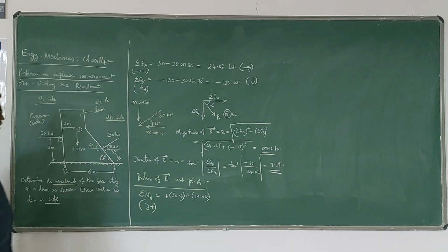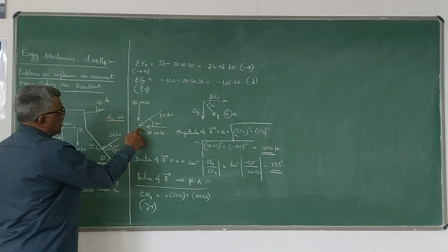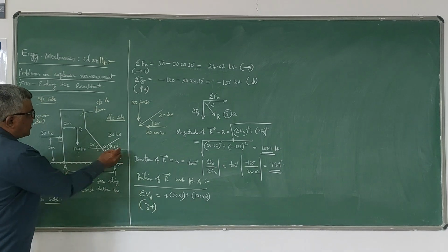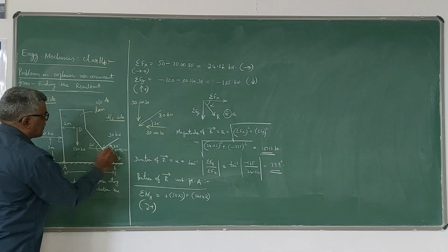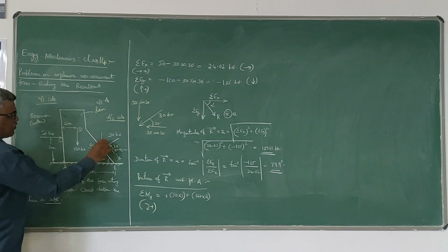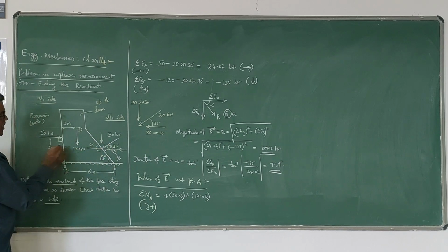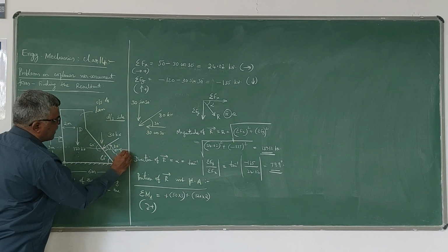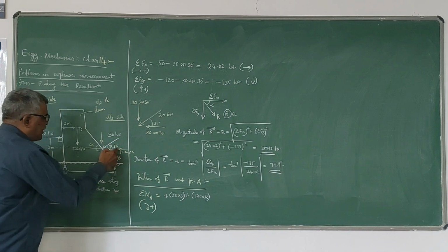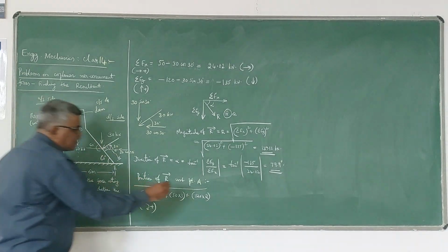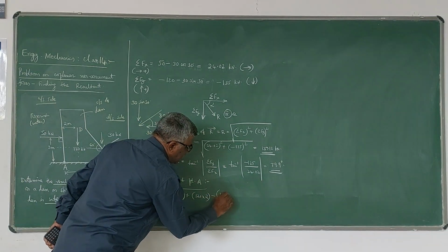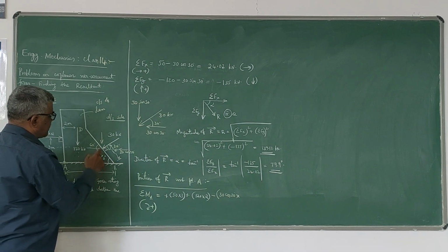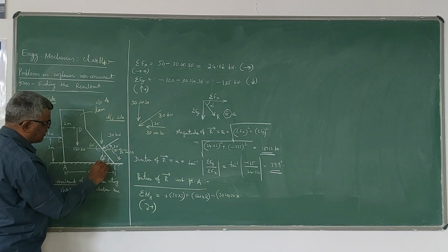Now coming to this force, there are two forces here. Now you should be careful. This horizontal force and this vertical force are components of the inclined force. If you extend the horizontal force, which is 30 cos 30, it is giving an anticlockwise moment about A. So minus 30 cos 30 into the distance, and the distance is this vertical distance. This is where you should be very careful.